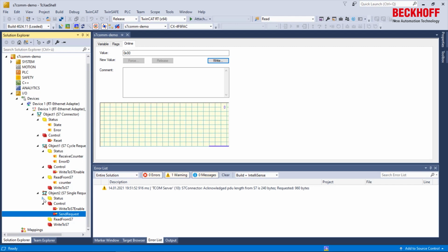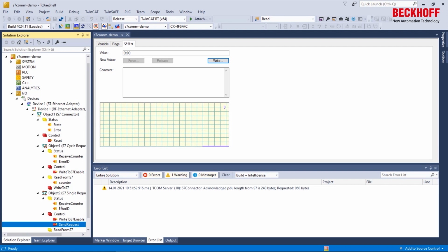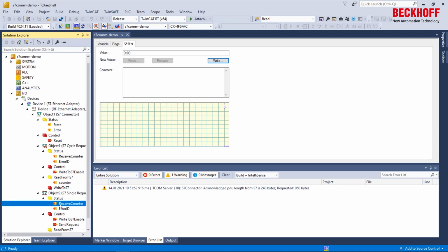If sendRequest is one increment higher than receiveCounter, the request gets triggered. PLC implementation is now straightforward. If I want to trigger a request, I increment sendRequest and wait until sendRequest and receiveCounter are equal.